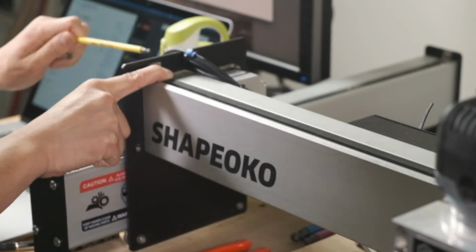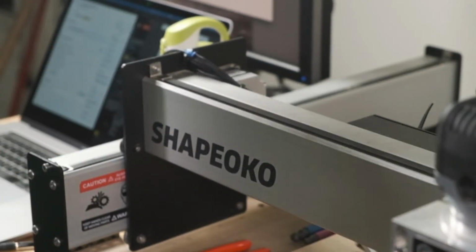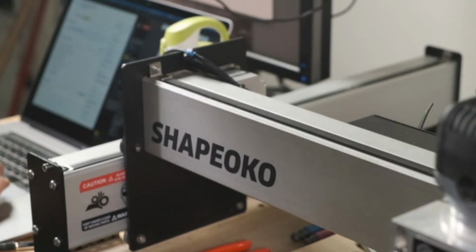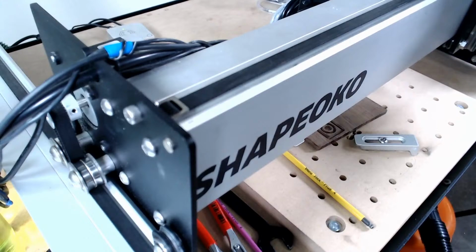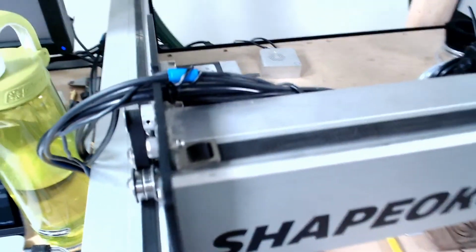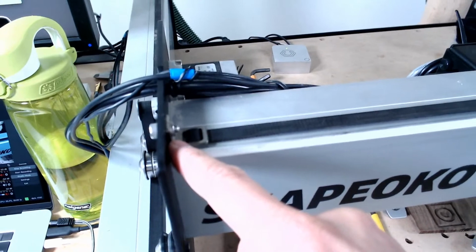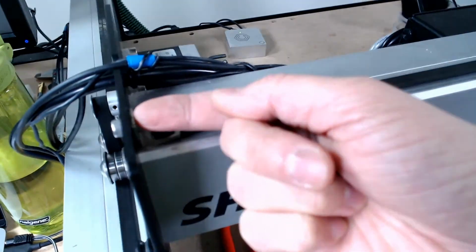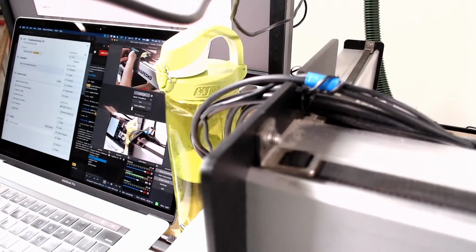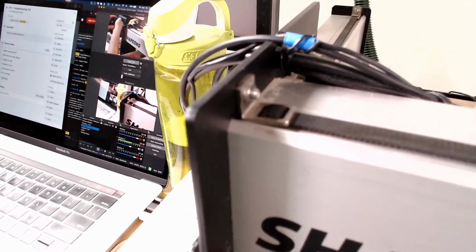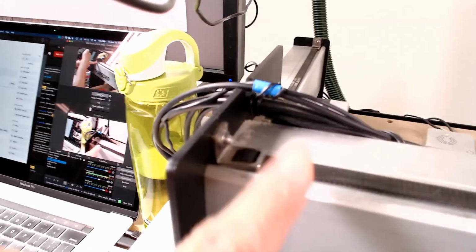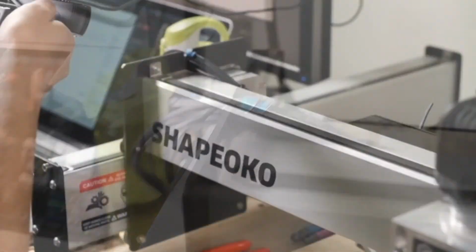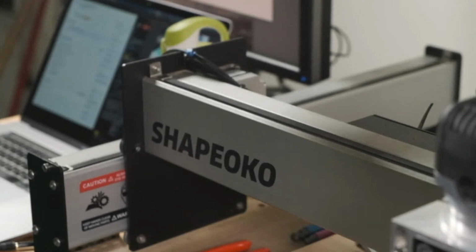carriage plate. So let me try giving you a different view of this. I don't know how well this is going to work. This might be nausea-inducing, but we have belt clip with screw. Just make sure that top edge of the anchor is touching the carriage plate. Otherwise, the long end of it's going to lift up and let your belt out. Okay. No more shaky cam.